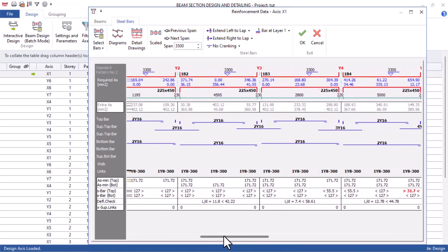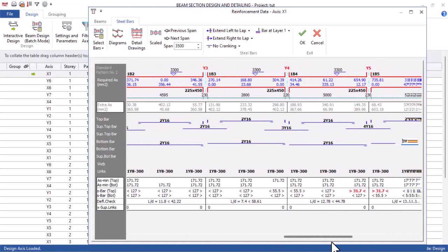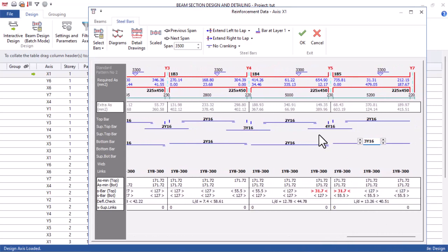So we move and you check your reinforcement. With this, you can see we are getting 16 mm reinforcement. I think cost wise it is a bit cheaper compared to designing with 25 and 16 for your model. So you need to take note depending on the model you're doing.